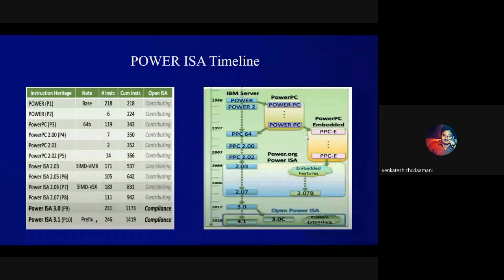Coming to the A2I, its instruction set is not compatible with all of the ISA, but the A2O has the full set of Power ISA and full architecture compliance. There can be certain levels of compliance as part of Power ISA, like decimal float, any of the floating-point purposes, and SIMD architectures.